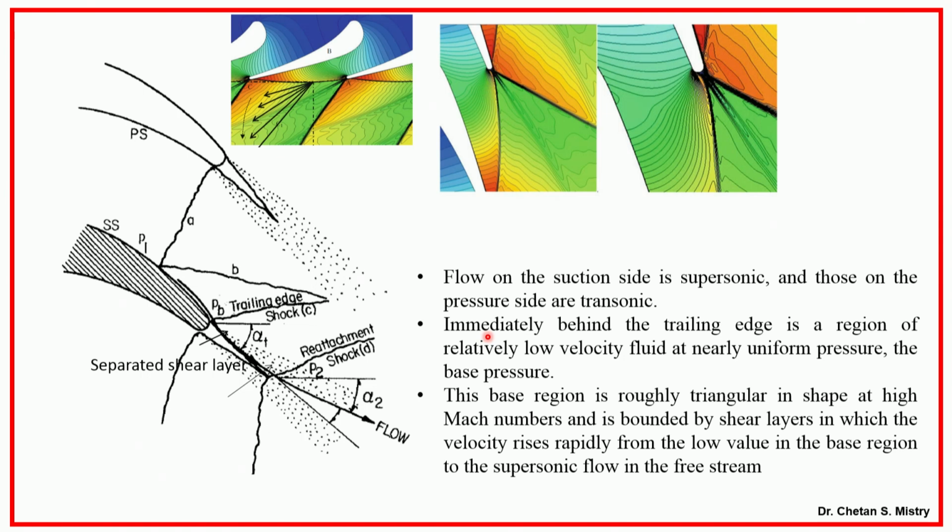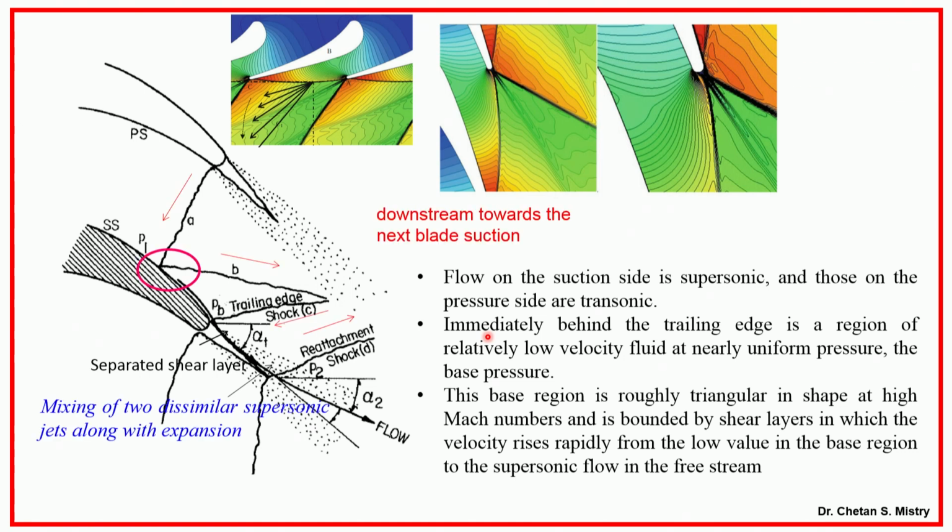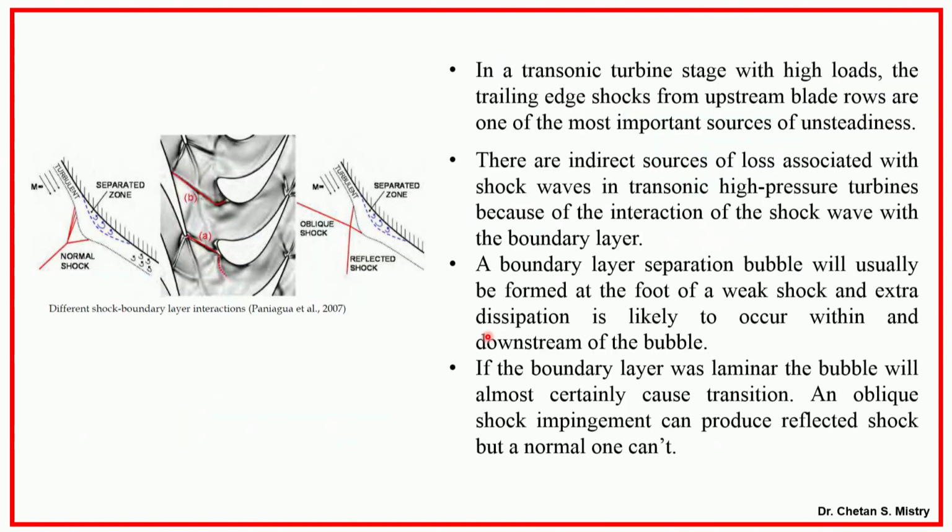So, this is what we have discussed earlier in terms of formation of my shock. It depends on the kind of design I am having, and the kind of trailing edge I am having. Now here, this represents what we were discussing in terms of shock. This shock gets reflected here. As I told, it will be striking on my suction surface.